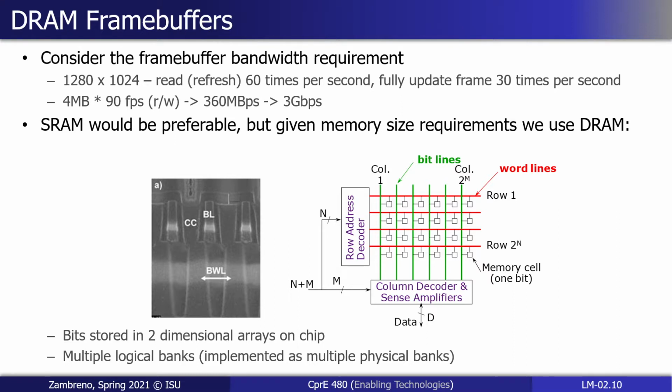So we go back and forth with that visualization, right? When thinking about a frame buffer, it's nice to visualize it as a two-dimensional data type. Our screen has a certain horizontal and vertical resolution. That's a nice way to visualize it. And then I always keep mentioning, well, yes, it's two-dimensional, but ultimately you have addresses in memory that are sequential. So there's a little bit of that array math that you have to do at some point along the way, given an XY location on screen, we could do the math: X times vertical resolution plus Y gives the actual linear address in our memory.